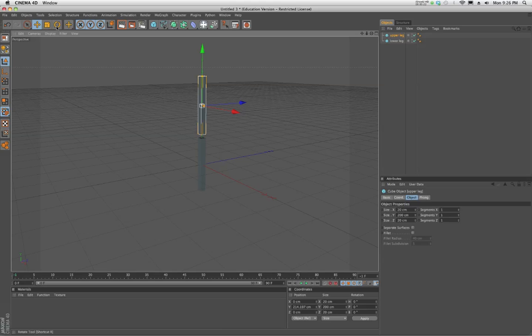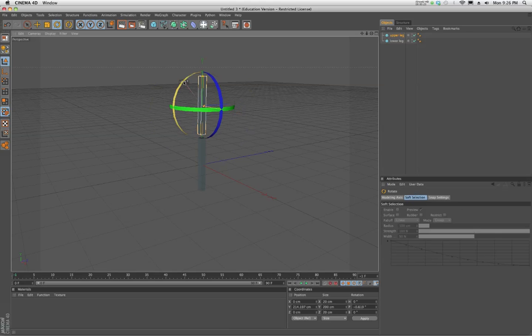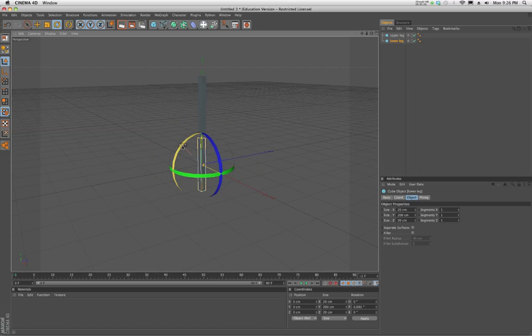Right now, if I go to the rotation tool and I rotate this object, it's rotating around its own center. And I want this to rotate more where the joint should be. So if I grab the lower leg and rotate it, there's kind of a breakdown in the fundamentals of the way the mechanics work. What I really want is for the pivot point to be right about where the knee is, so that when I rotate this object, it's rotating around the knee joint rather than the center of the object. There's a couple different ways to move the pivot point.